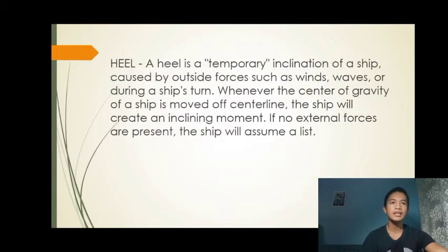Heel. A heel is a temporary inclination of a ship caused by outside forces such as wind, waves, or during a ship's turn. Whenever the center of gravity of a ship is moved off the center line, the ship will create an inclining moment. If no external forces are present, the ship will assume a list.